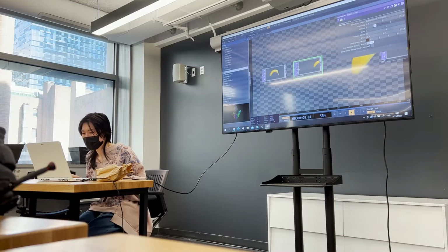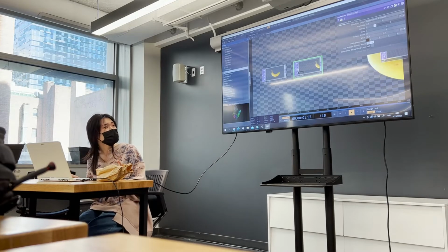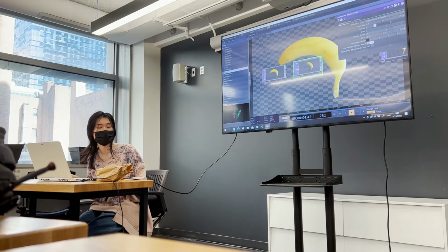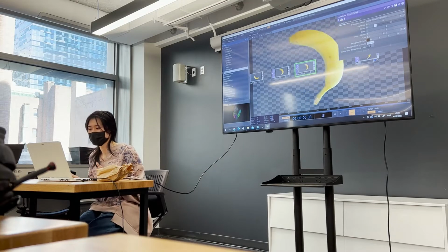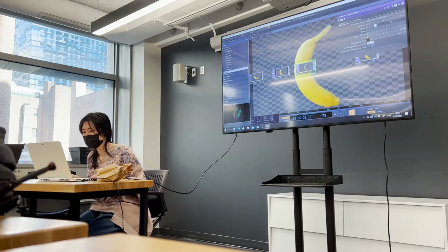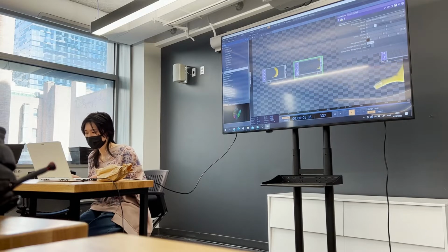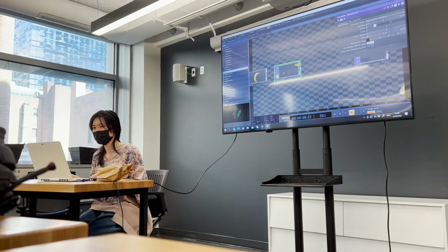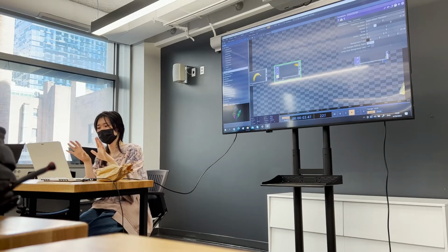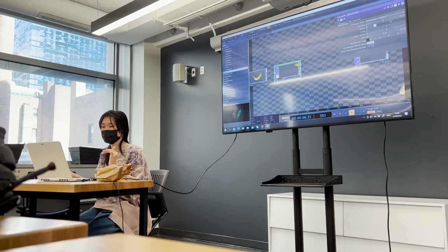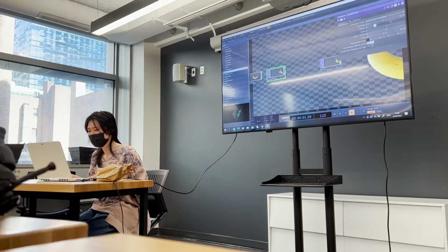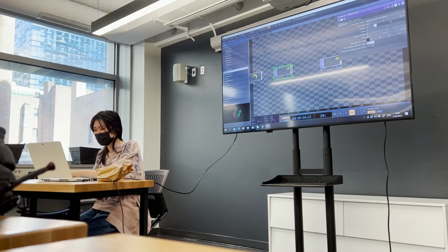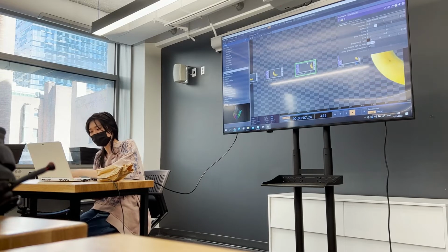And the one I'm going to talk about is the bypass, which essentially, if you click on this node, bypasses the process, basically turning it off. Now it's just functioning like a null node. And the last one is lock. When you click it, you lock the output of it in that frame, and it's not going to update from that point, but you can also unlock it. And for now, we're just going to throw away this transform because we don't really need it.